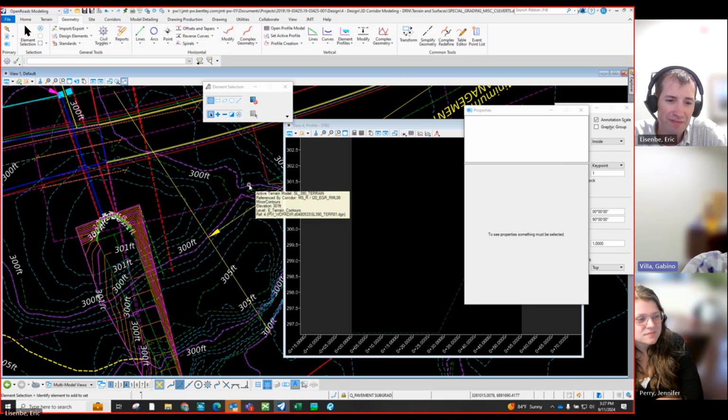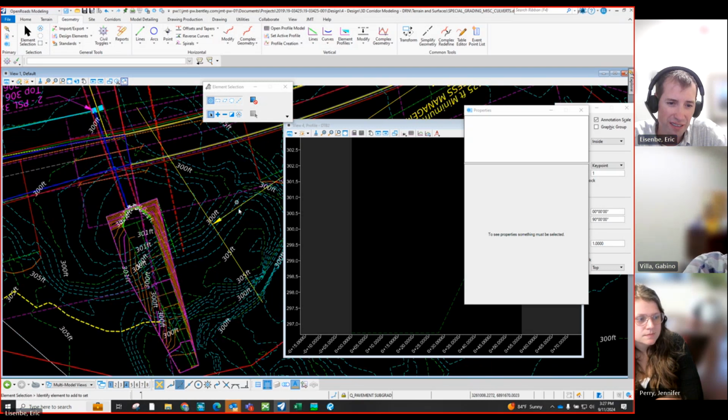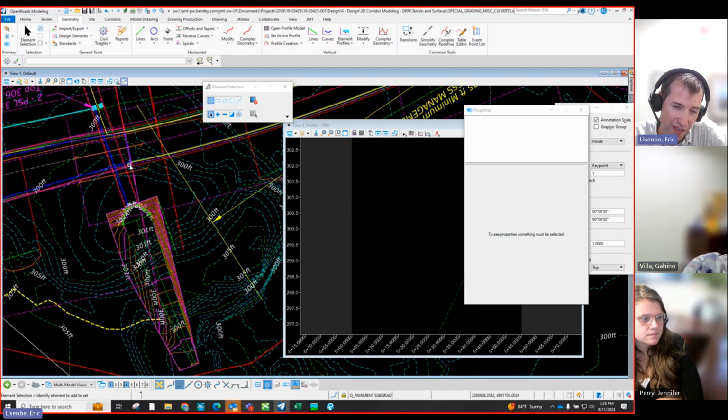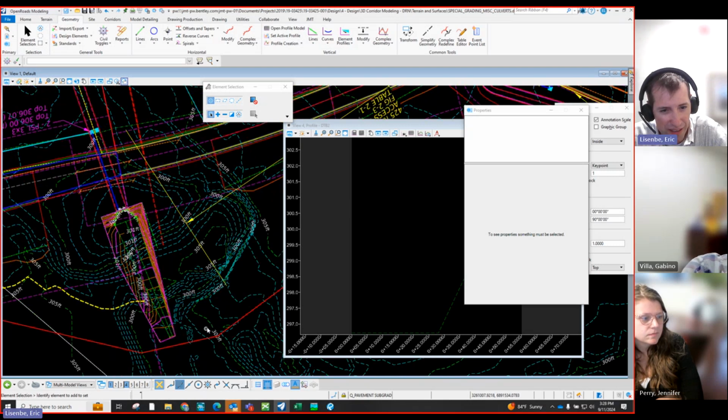And on those contours, all those contours need to tie into another contour, right? Yes, essentially. Eventually it needs to tie into existing ground. So this stuff, I think it's probably close enough to where you come down here and meet it. It's pretty much what you have already because it's probably not changing that much. And then we hit here, and then these edges, that's where I would build my boundary and probably push it a little closer to the right of way, so it can be as smooth as possible.